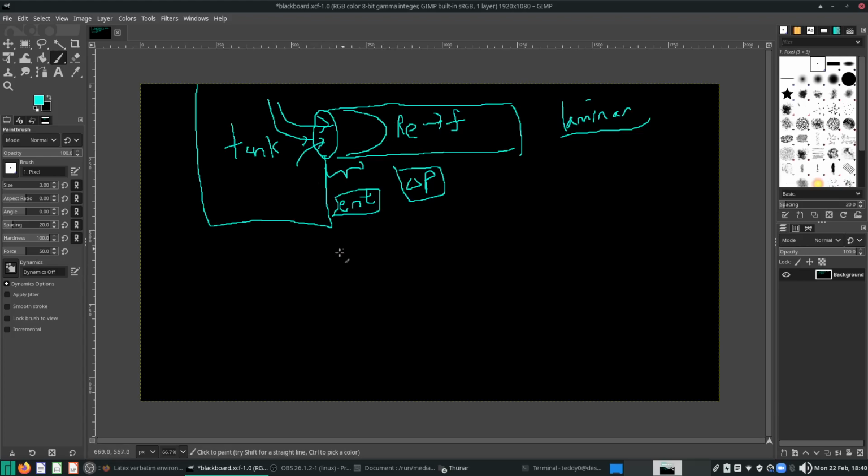Laminar flow will often have this parabolic shaped flow profile, but at the entrance region you will not have this sort of flow profile. However, at the entrance region you would also have some sort of pressure drop, but it's not going to be well accounted for using the traditional Moody's chart. So how are we going to deal with that? And the other reason you want to study boundary layers is to give you an understanding, especially for external bodies.